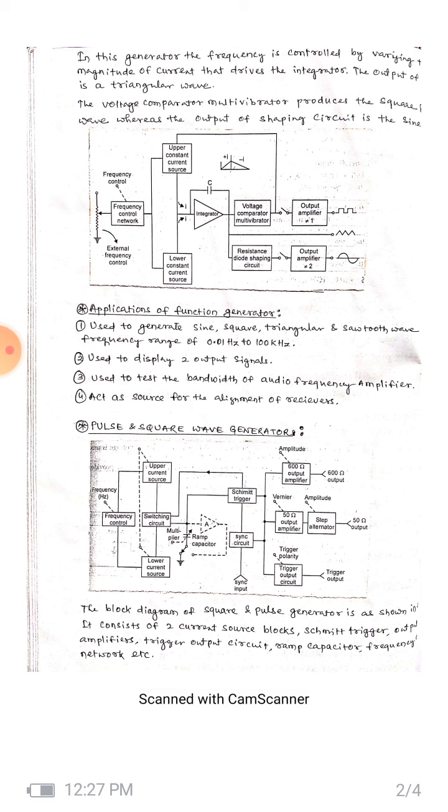When the capacitor charges to peak, it starts discharging at a linear rate controlled by the lower current source. The entire process is repetitive. The schmitt trigger provides a negative pulse at a continuous rate.